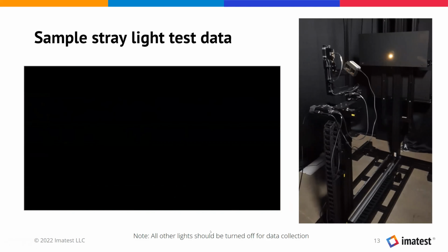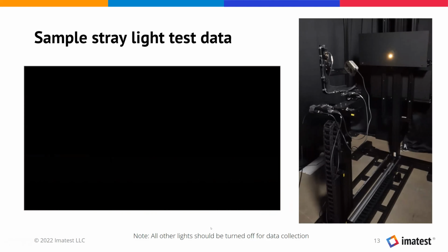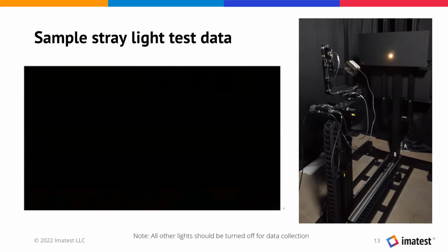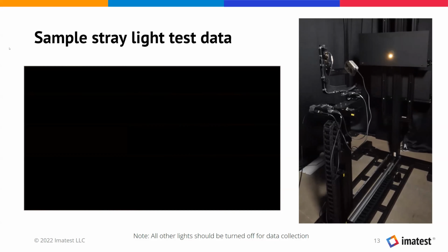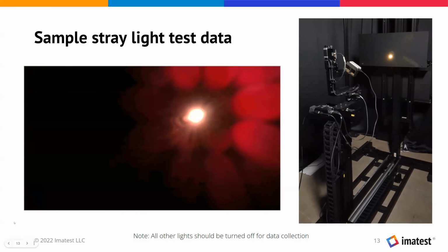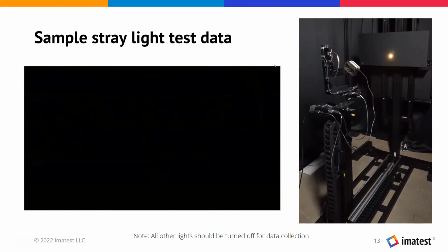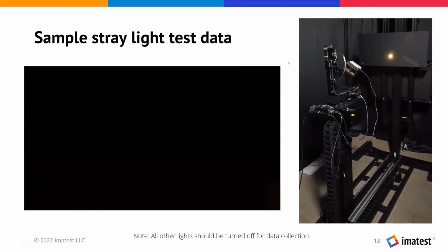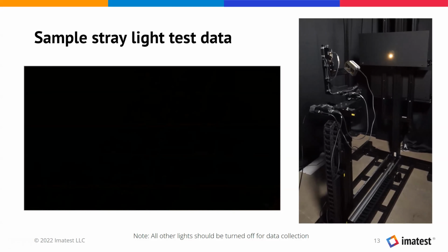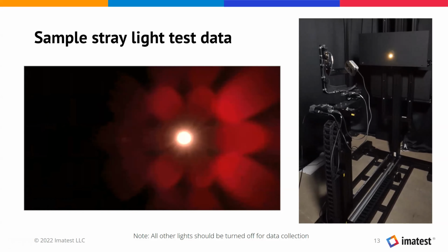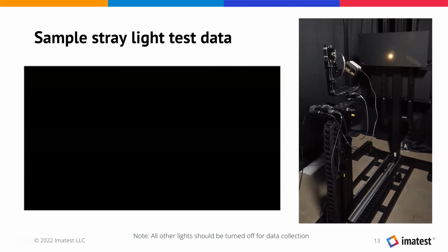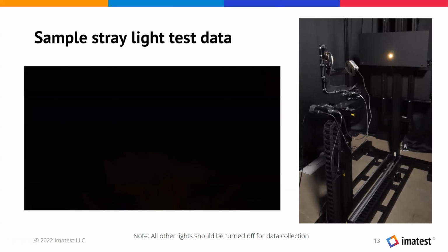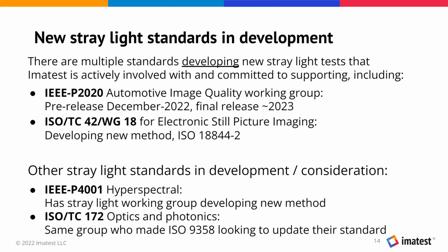You could test with just a single axis sweep, but with that, you're assuming radial symmetry, and you might have radial asymmetry, or asymmetric stray light performance due to imperfect optical design. You might have some deviations on the surfaces of the lens that only cause stray light at specific azimuth angles and field angles. So for comprehensive testing, you would want to position this light source at as many positions as possible in and outside the field of view. But that will take time.